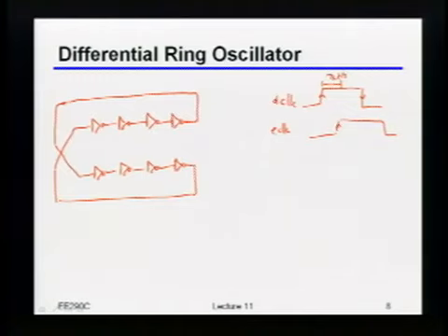The way you ensure it is you literally just throw something in there that forces it to be that way. The most common way to do that is to add some cross-coupled inverters like this. Now, by the way, can I really just add it in one point like this, or do I have to add it everywhere? Yeah, you have to add it everywhere, because remember, you wanted all of the phases to actually match, because you're trying to use all of them. So indeed, now I have to start adding this in every single point. It ends up looking something like that.